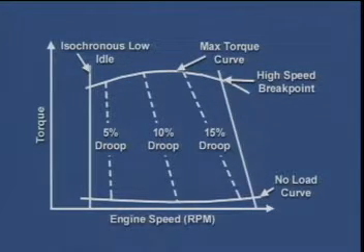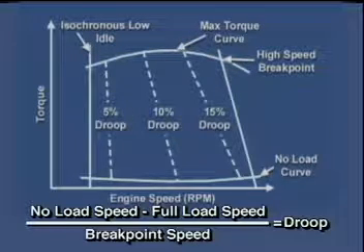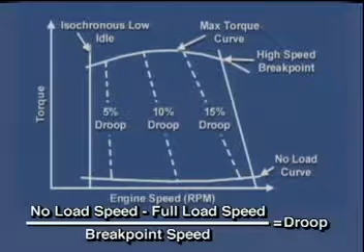It is often desirable to allow the engine speed to gently decrease with the application of a load to enhance drivability. This prevents jerkiness and protects mechanical components attached to the drivetrain from damage due to sudden applications of torque from an engine that is aggressively attempting to maintain its commanded speed. For these reasons, Quantum uses variable droop in the governor algorithm, where droop is defined as the difference between the no-load commanded speed and the full load commanded speed divided by breakpoint speed. The ECM calculates the proportional amount of droop at engine speeds between high and low idle.